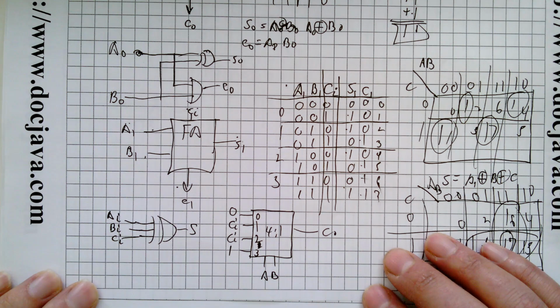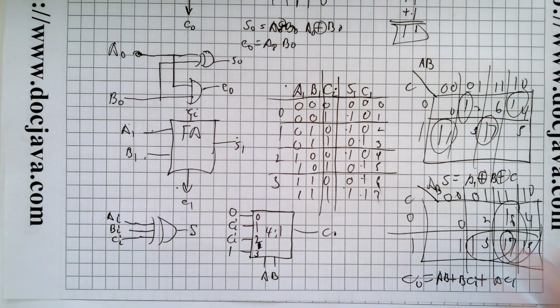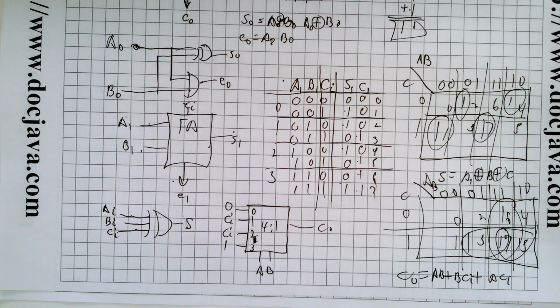There. That's actually easier because you assume you have a 3-input exclusive OR gate. Okay, I know they don't have 3-input exclusive OR gates hanging around in the shop. So if you wanted, you could implement it with the 4-to-1 multiplexer. I just got lazy. What do you think of that?